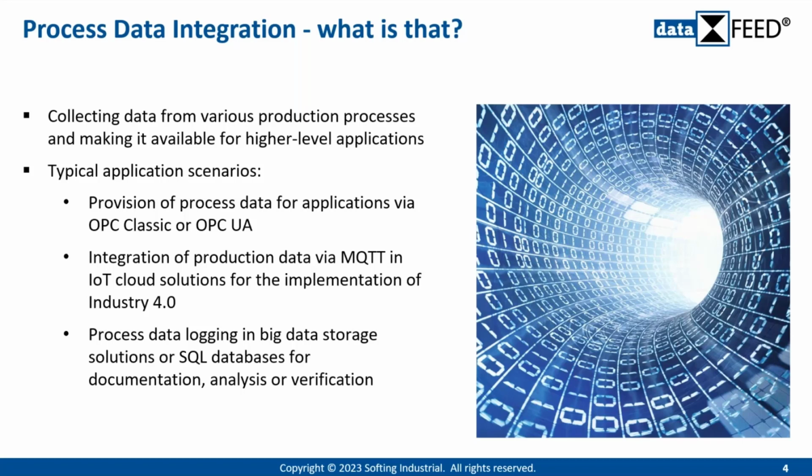Typical scenarios of process data integration solutions are provisioning of process data for applications via OPC Classic or OPC UA, integration of process data via MQTT in IoT cloud solutions for implementing Industry 4.0 scenarios, and last but not least, process data logging in big data storages or SQL databases for later documentation, analysis, or verification. These are typical process data integration scenarios.